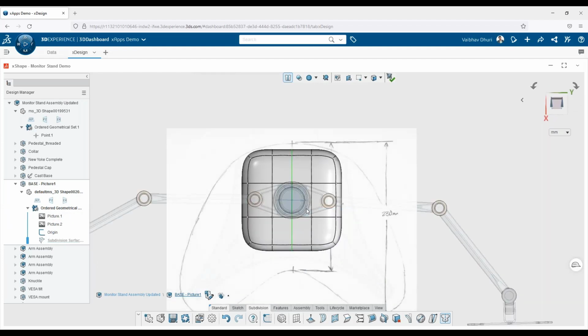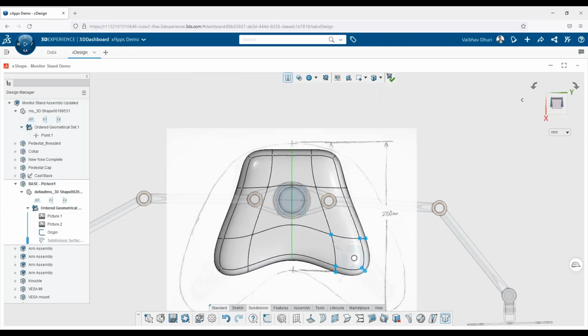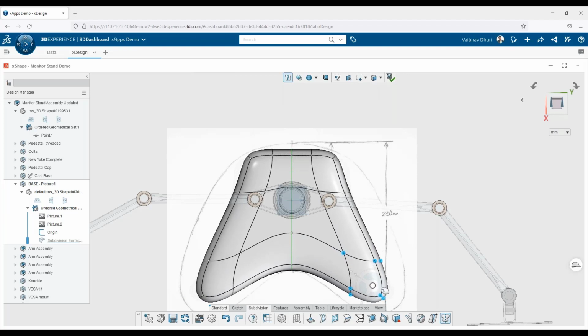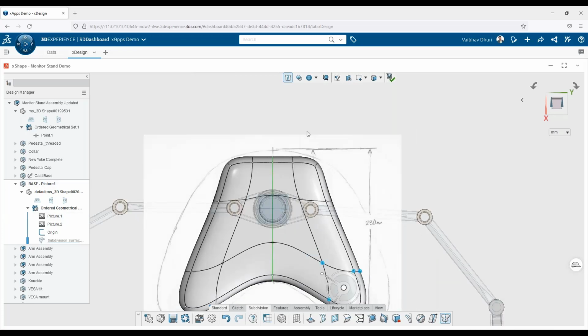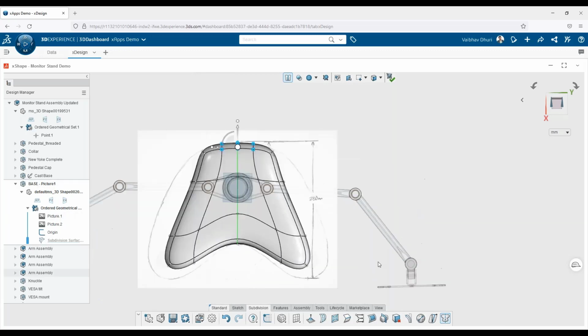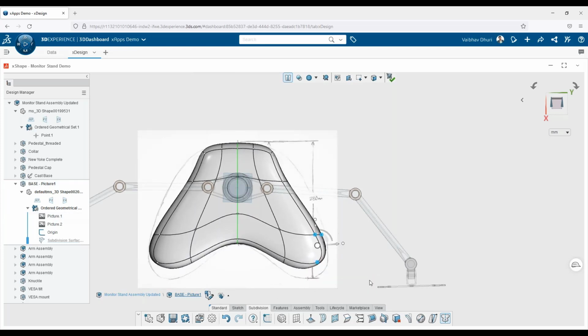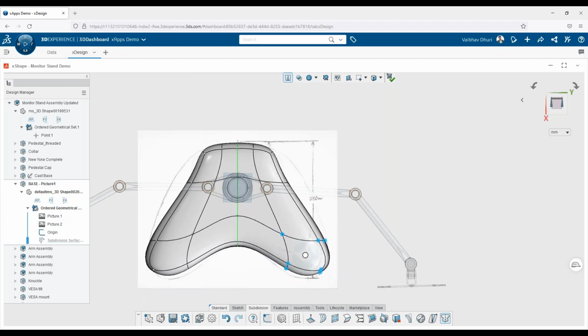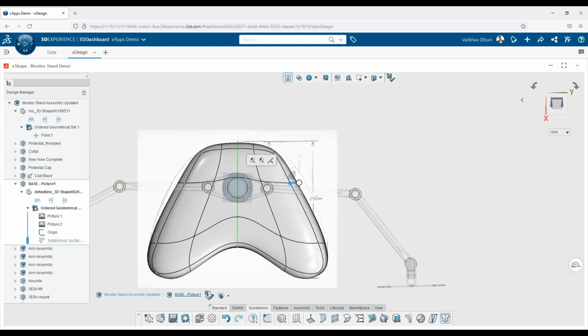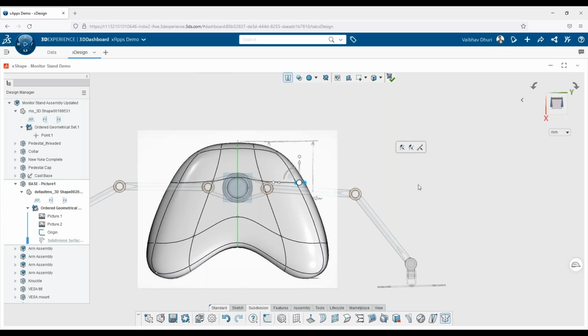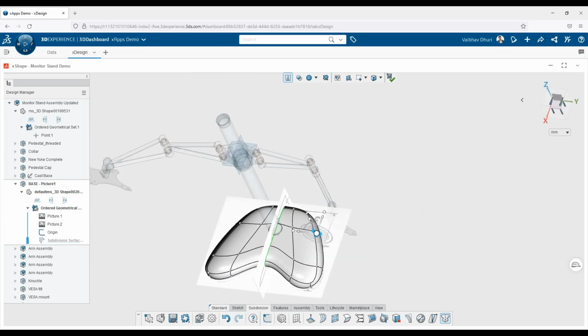Here I'll just select these entities. First of all, I need to turn on my selection. I'll select these entities, and pushing and pulling it, I'll create this complex shape very easily. And I need to map this down to the background sketch. So here I'll select a few more entities, push them up to match it here, and spreading this out, and then selecting everything, pulling this down so that it matches. And this particular section I'll pull out to match it here. You can see within seconds, not even minutes, within seconds I've covered everything.